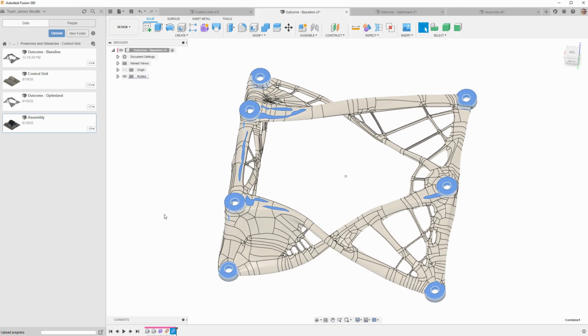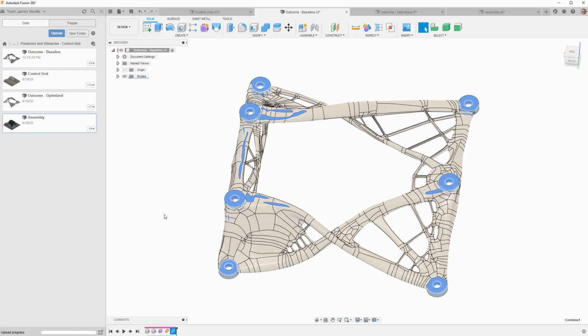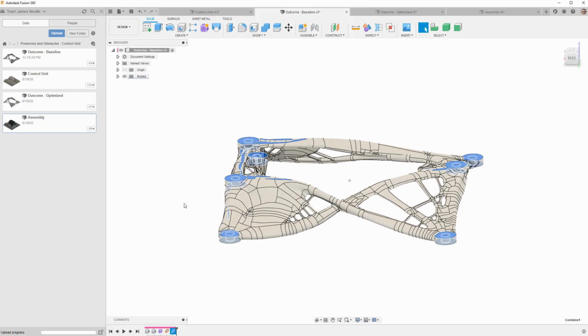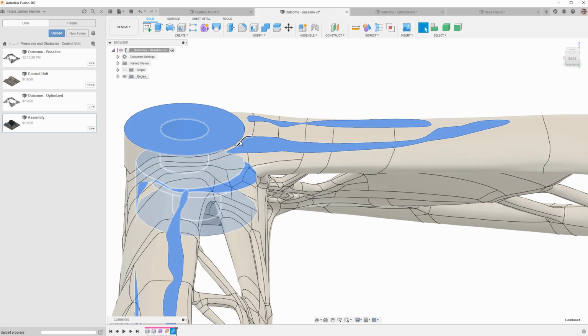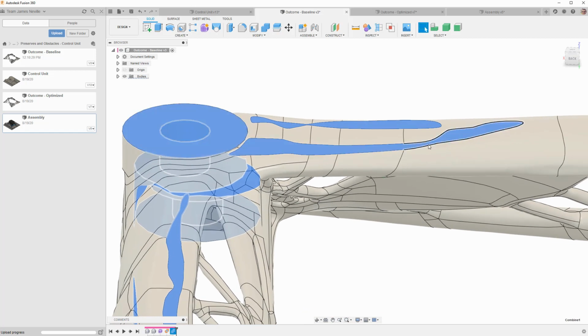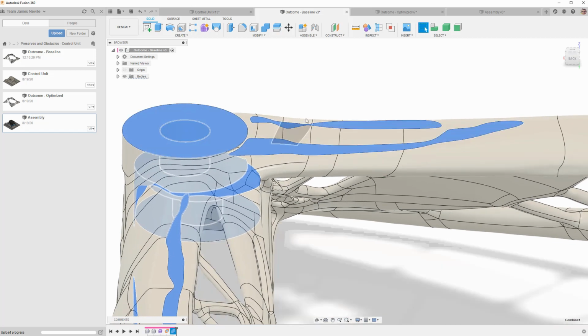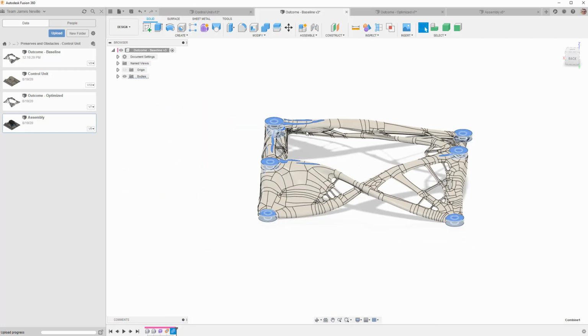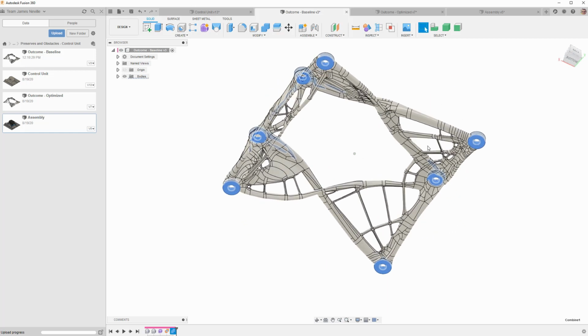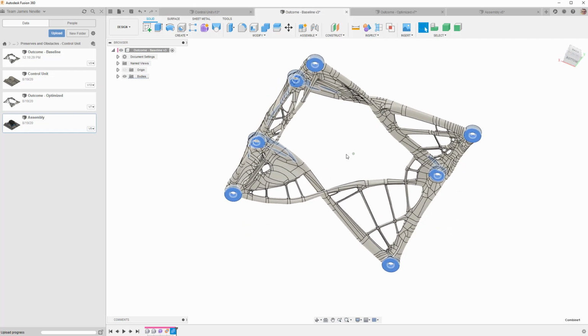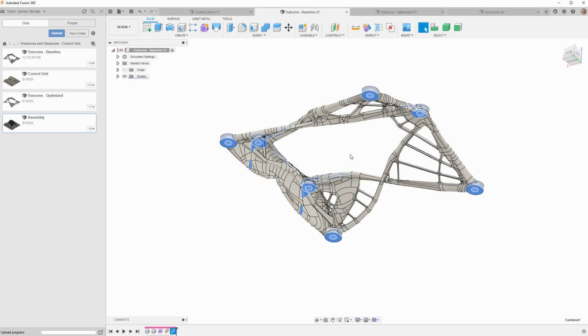This shows everywhere where the model has been cut away by the obstacles. So you can see it actually went right up to the top. A portion of this went right up to the top and actually touched the underside of that control unit, which I don't want. I want my contact at the mounting points, not anywhere else. So that's not good. I don't see any contact on the bottom side. So it actually stayed off the sheet metal pretty well.